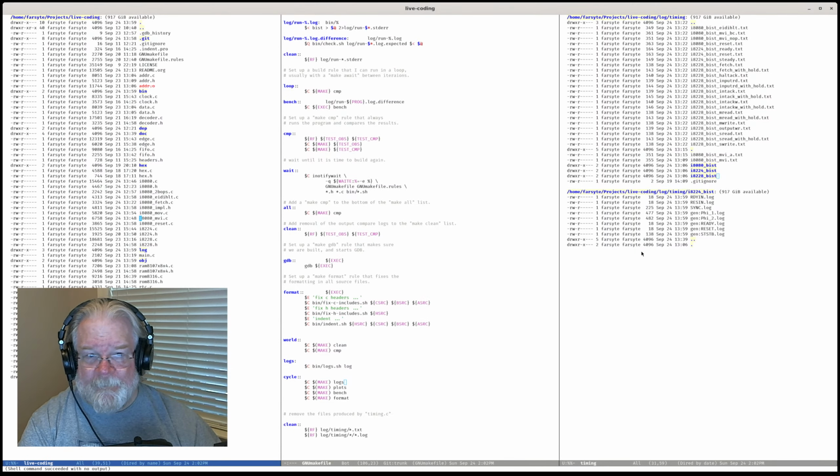So MOV. Now MOV is going to use MVI instructions to test MOV. The other thing is we don't need to test all 64 of them. We need to have at least a test reading from each one, at least a test writing to each one.